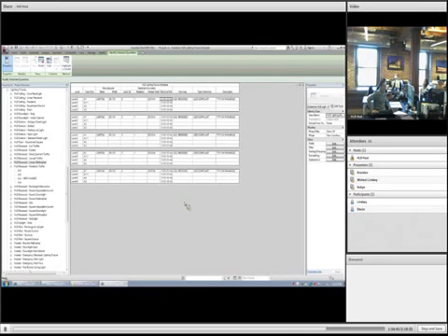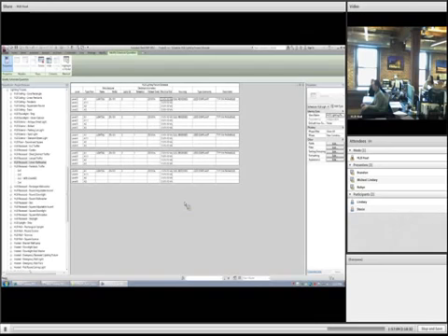We did some arrays. I just want to do some other things. Okay. I would also say one of the things in terms of best practice as our team, before sending a package out similar to CAD, we should be purging. Because inevitably you get crap in there that you don't need, and to keep our model size down, to try and clean up as much as possible for our clients, we should be purging once it's all said and done. So something good to keep in mind.